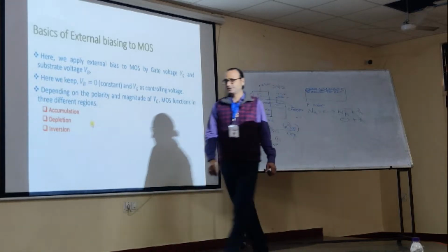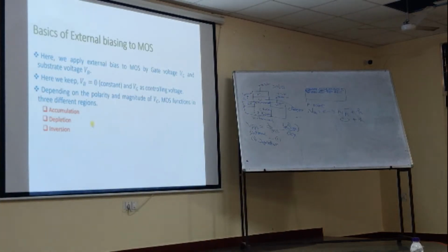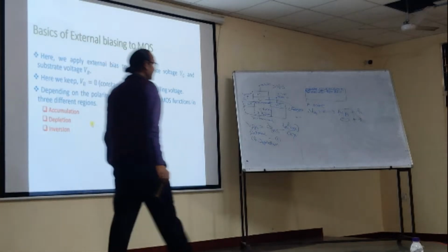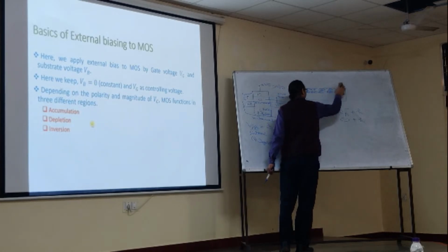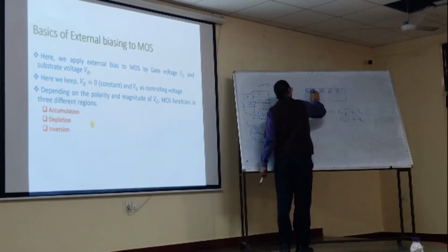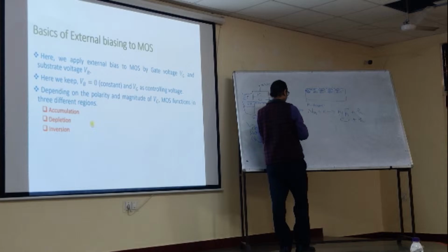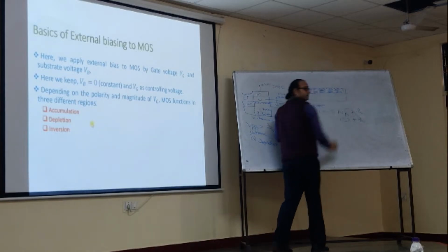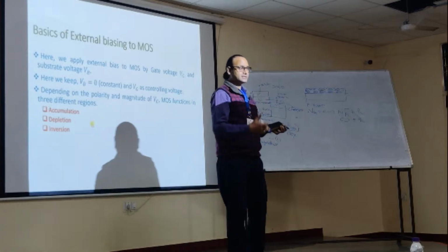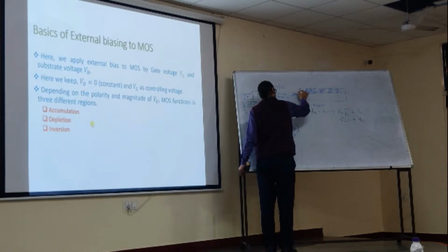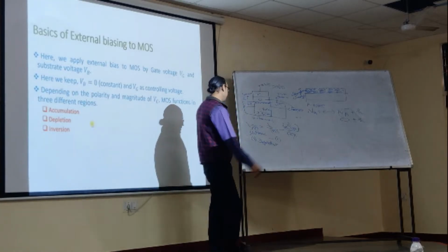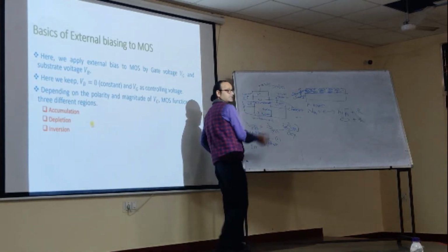Now I said first there will be depletion. It means electrons will recombine with the holes and they will become neutralized. You know, hole is a deficit of electron, right? What will be left behind? These charges. Unfortunately they are not free charges. They are fixed charges. Fixed charges mean depletion charge. So this is the depletion charge, right?